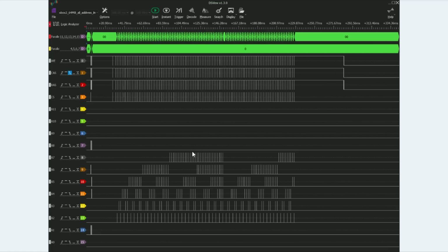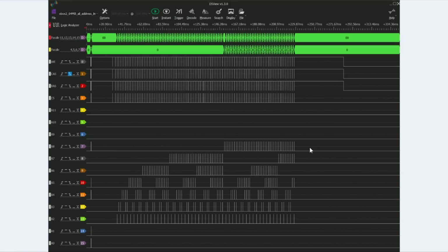This means there are 8 column bits, because it's A0 to A7. Then I switch to 9 column bits, and this is amazing. We can see that now A8 is used at that rollover point, where previously the value just went back to 0. Now we roll over to A8. A8 becomes active. We have 9 column bits. So this looks really good. Also, this took a long time to develop such a clear view as this.